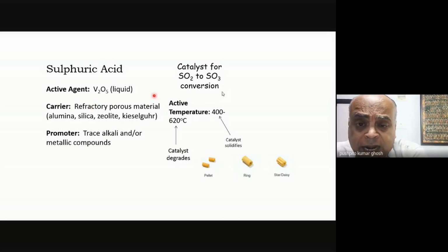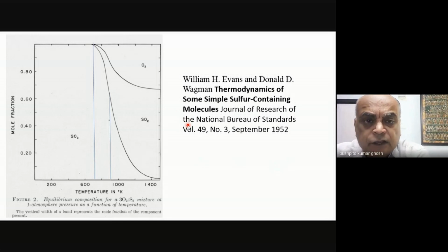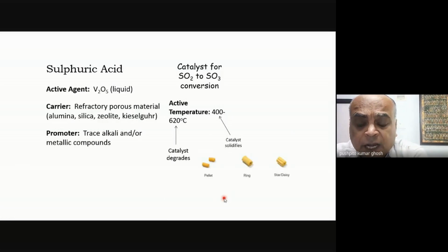Now, on the other hand, if we try to do the reaction at 650 or so, again I have a problem. Now my problem is not the rate of the reaction, my problem is the conversion of the reaction. Okay? Because my conversion is going to drop. And you have seen how steeply it drops with temperature from this plot. Okay? So look how steep it is, how it's falling off with temperature. So this is the dilemma.